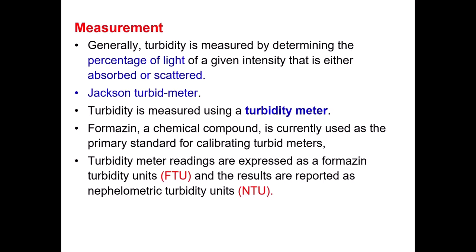the location and season. In the United States, the EPA, Environmental Protection Agency, states a maximum turbidity of 1 FTU for drinking water. This standard makes sure the water is safe, clear, and pleasant to drink.